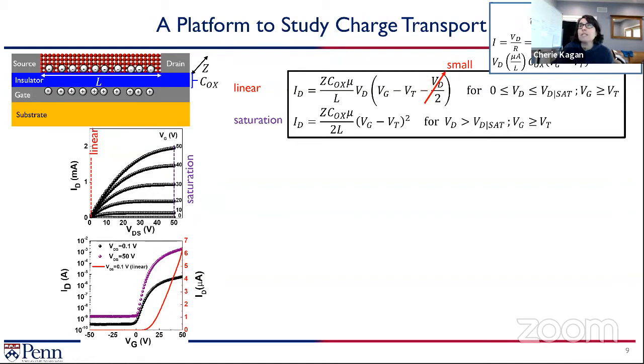equation comes from, because the key here in a field effect transistor is that this carrier concentration is modulated, as you saw in my animation: as I change the gate bias, I'm going to introduce more carriers. Or, if you know the equation for a capacitor, you know that charge equals capacitance times voltage. So here it's really about the carrier concentration. This voltage is how much above threshold I start to introduce charge. And if I plug this in for the carrier concentration, you'll get an equation that looks very reminiscent of the one that you see for the transistor.